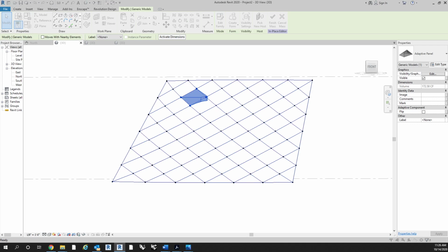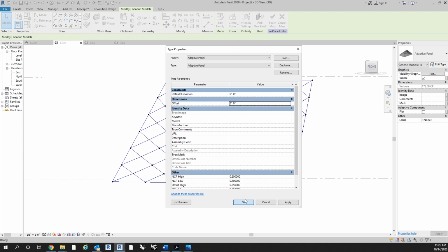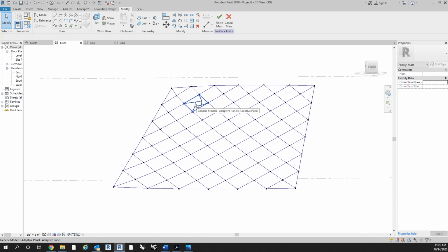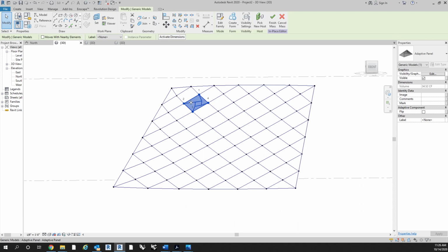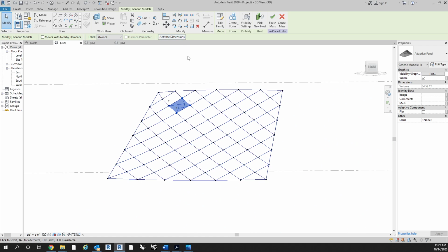We can probably adjust some of the parameters. Sorry, this is in another window. I changed the offset to 2 feet. All right. Now, if you have it placed and you want to repeat this pattern across every instance along this surface where these conditions are met, up at the top, where there's typically an array button under Modify, there's a Repeat tool.